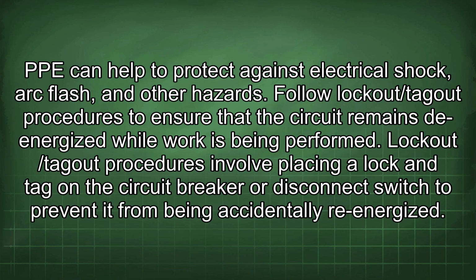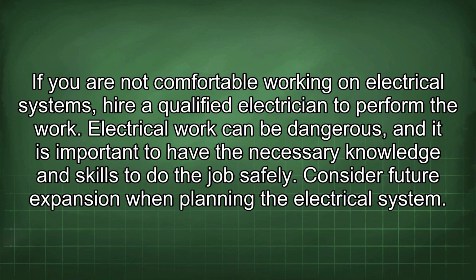Follow lockout/tagout procedures to ensure that the circuit remains de-energized while work is being performed. Lockout/tagout procedures involve placing a lock and tag on the circuit breaker or disconnect switch to prevent it from being accidentally re-energized. If you are not comfortable working on electrical systems, hire a qualified electrician to perform the work.